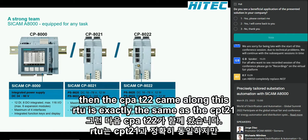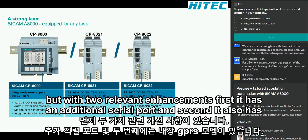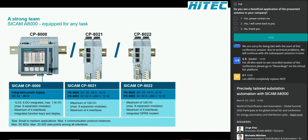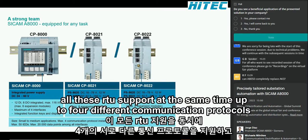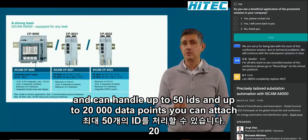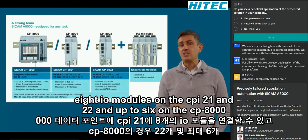Then the CP8022 came along. This RTU is exactly the same as the CP8021, but with 2 relevant enhancements. First, it has an additional serial port, and second, it also has a built-in GPRS modem, which means that this RTU comes already prepared for wireless communication. All these RTUs support at the same time up to 4 different communication protocols and can handle up to 50 IEDs and up to 20,000 data points. You can attach 8 I/O modules on the CP8021 and 22 and up to 6 on the CP8000.